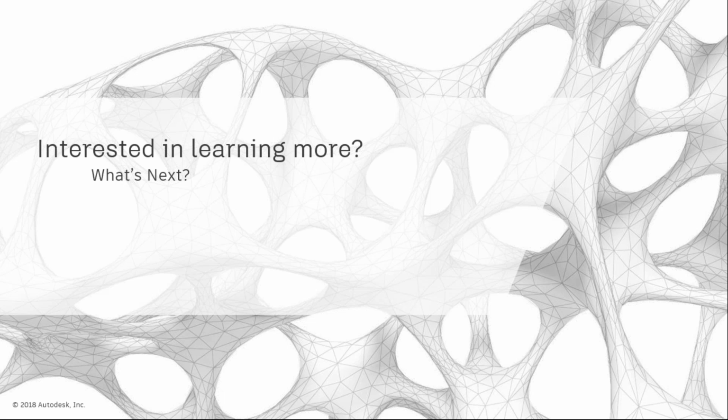Is there a possibility to optimize the iteration of generative design for 3D printing? Yes, we have it listed as additive manufacturing. That is the manufacturing constraint that you would enable from a 3D printing perspective. You have a few details you can specify there, namely the overhang angle.